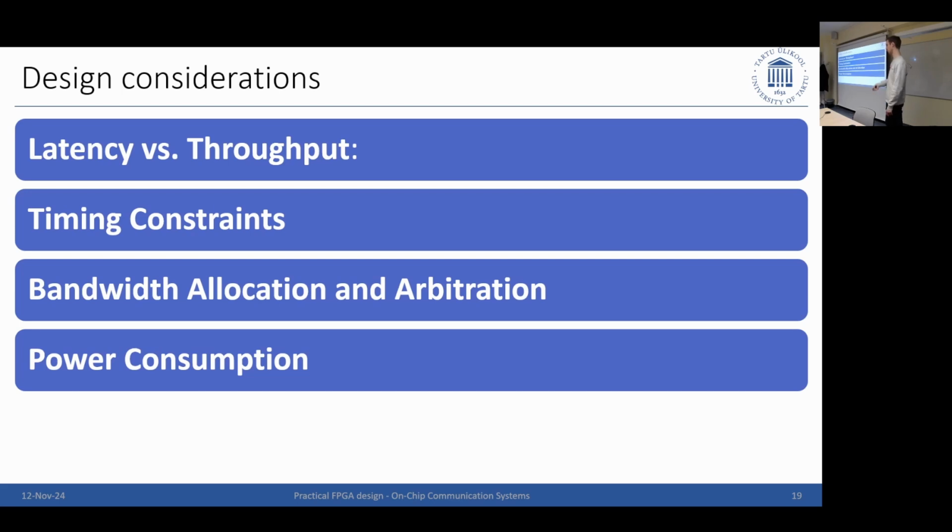If you have something mediocre where you have data and just control on it, you want to use the full AXI. But if you just want to trigger to get data and then get a very high response, then you have least overhead with an AXI Lite and an AXI Stream, and then you get basically the lowest latency with the highest throughput. But it's something which you always have to trade off. Network systems are never that simple that you can just choose the one or the other. You probably want to use a mix of it.